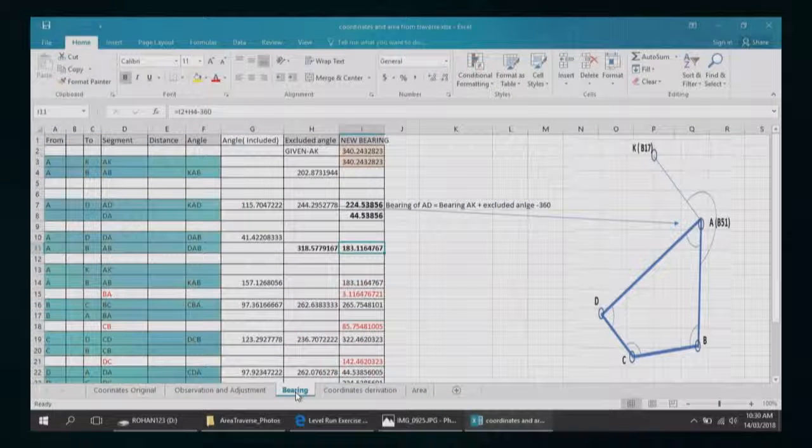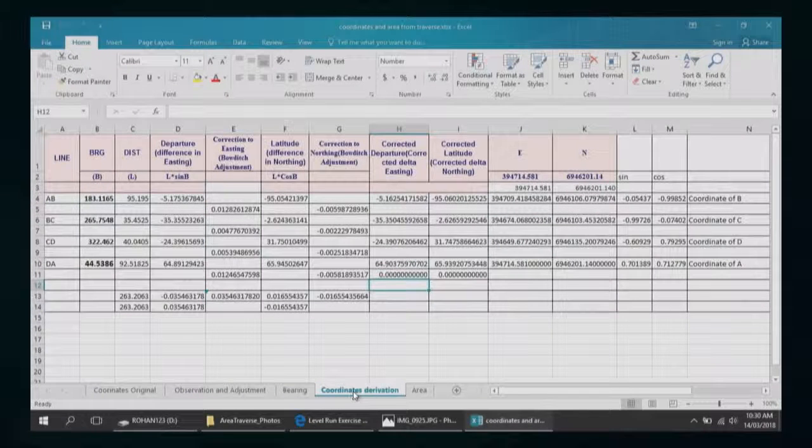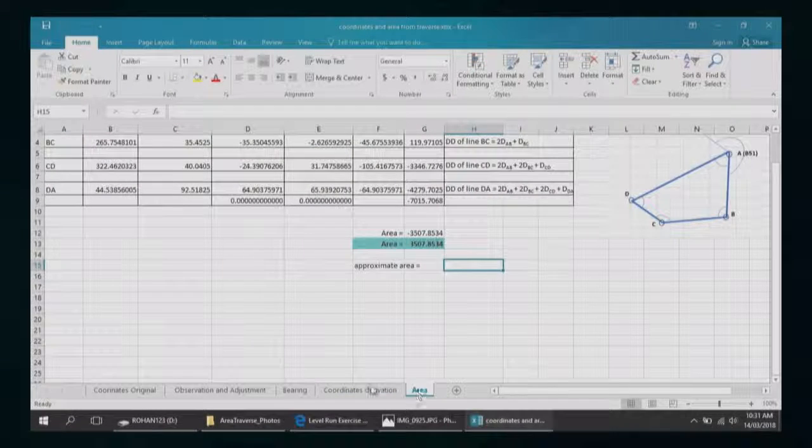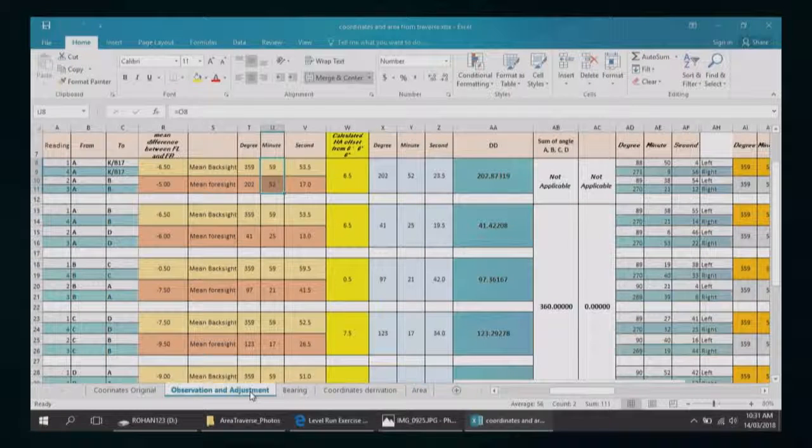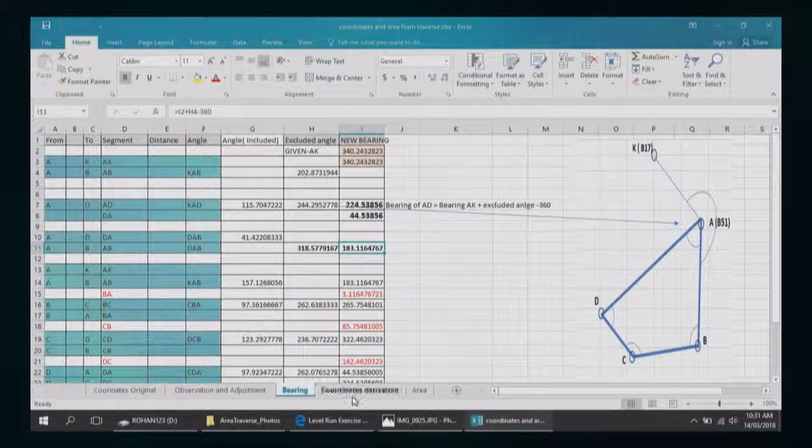We then go and start calculating the coordinates of the other point, the easting and the northing, and we apply some trigonometry and the area of a trapezium to actually get to this area. So there are three parts to this in which this resource can be built. One is going out in the field and recording the process of taking the readings. Second is understanding how those readings are used in these 4 steps. And the third part is revisiting the trigonometry and the math that sits behind this.